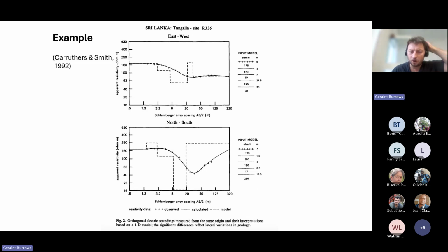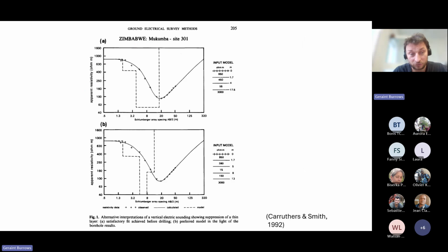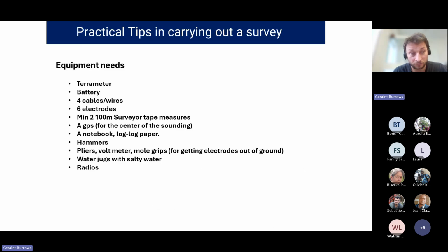Yes, I think it's a very good example of the variability of the subsurface, both laterally and at depth, and how that does impact on any reading. If you're trying to understand depth, it's going to be influenced by the lateral variability as well. It gives a good example of the uncertainty associated with using geophysical methods in general, but not to say that they're still not useful.